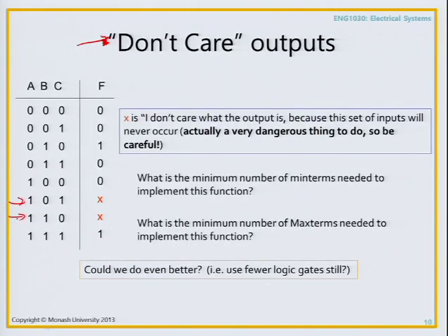So 10 decimal digits in binary, but you're using 4 bits, which means you actually have 16 different combinations of ones and zeros. That means you've got 6 left over. And in that example, for those 6 left over, you might say, I don't care what the output of that input combination is. In that case, I'm allowed to put an X in there, which is the standard industry symbol meaning I don't care what the output is.